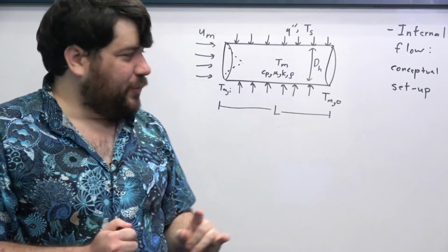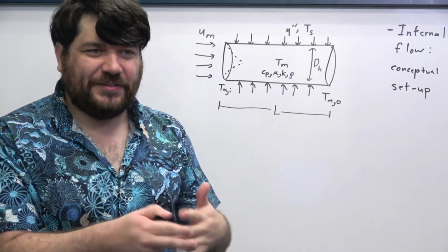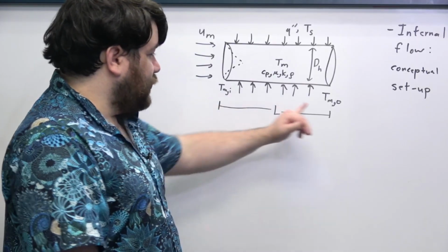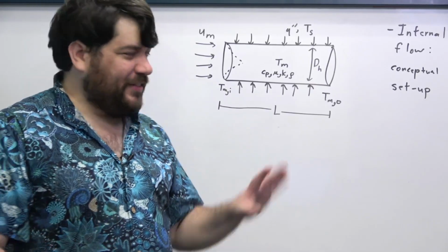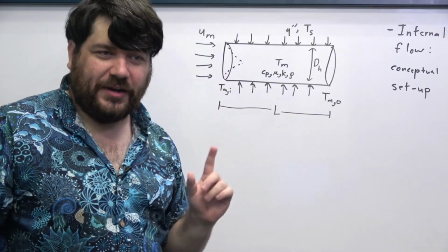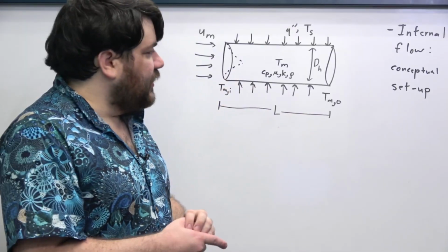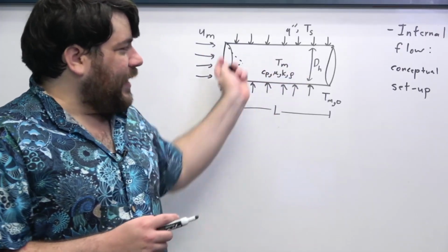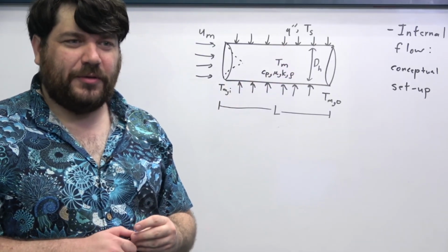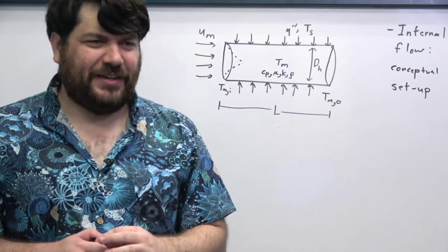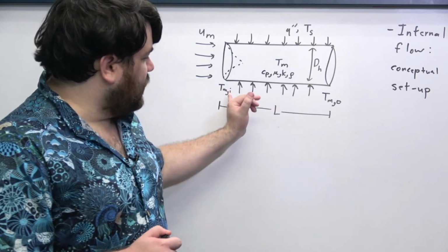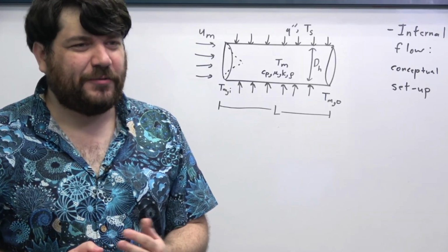and we further assume that the liquid is not generating heat, that there isn't some kind of chemical reaction that causes it to generate heat, and that the temperatures that we're describing here are steady, that nothing in this problem changes over time, at least not from the perspective of what we've drawn. If this is the case, trying to set up an equation that balances the energy rates inside of the system will tell me that the net heat transfer going in through the pipe is 0, which doesn't really make sense. Clearly heating or cooling is going on. This temperature is going up from TMI to TMO. So how do we account for it?